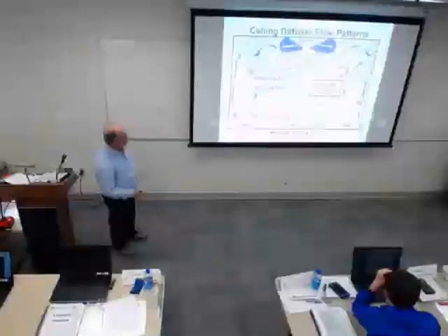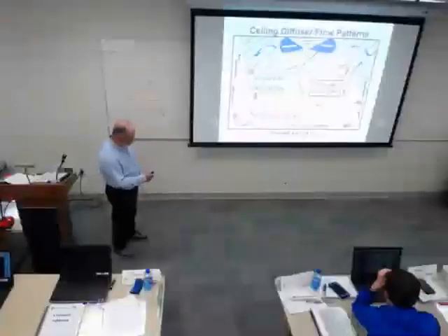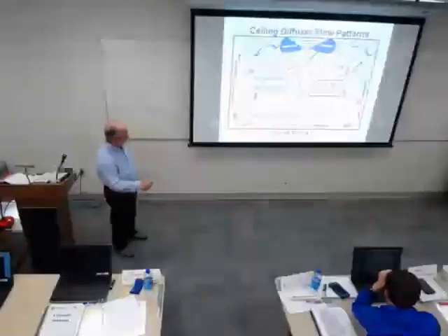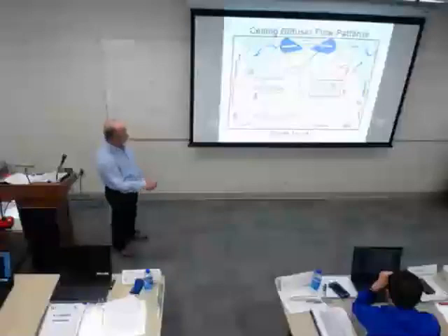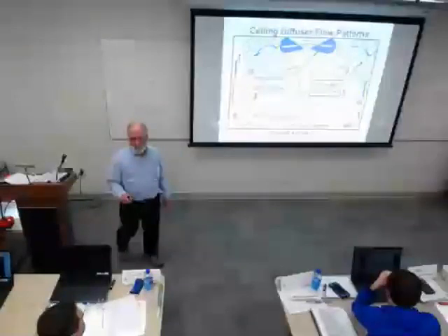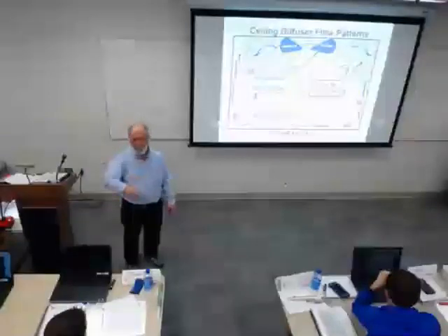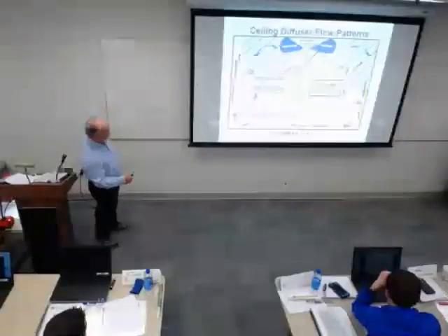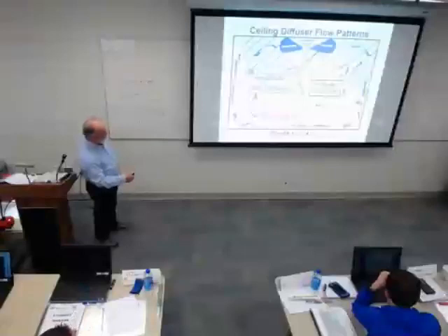Okay, so here we have air coming into a room. You notice the area of the jet, we have airflow that may not be really intuitive here, but you'll notice that we have air coming down the wall. We try to design so we sweep the wall a bit, and then we have air that circulates back up. So we generally have a circulation. We might have a couple of cells of that. Sometimes there's a third, like when we have cubicles: air going across the cubicles like this, air in the cubicles like that. That's part of the design, and part of why we pay the engineer to choose the diffusers that should be selected for the job.